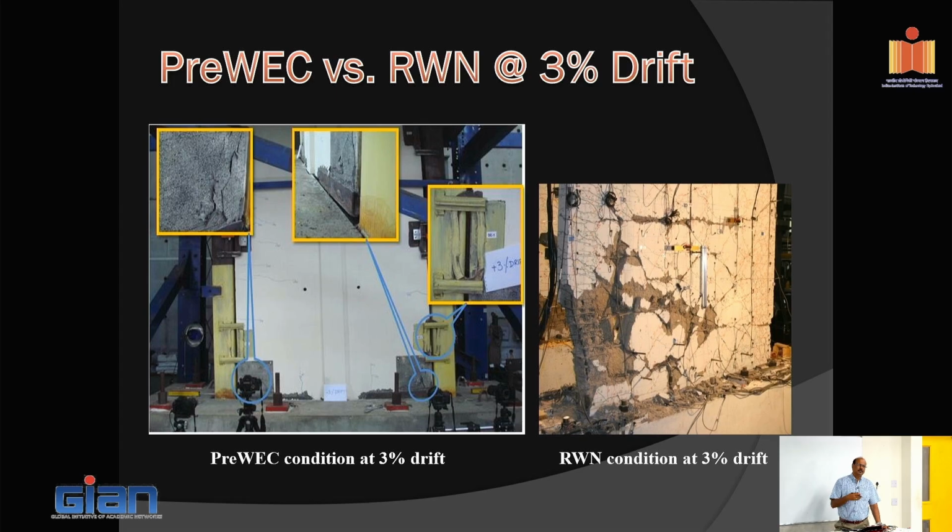So the concept of designing for resiliency became hotter after the Northridge earthquake in the US. And that's what kind of started displacement-based design and performance-based design. So you design for a certain performance depending on the type of structure that you're looking at. If the structure is not critical, maybe you go for the solution on the right side. If it's critical, you go for the left. What the precast industry wants to do is to show that for any structure, we can give you a solution cost effectively, or cost comparatively with the cast-in-place option.